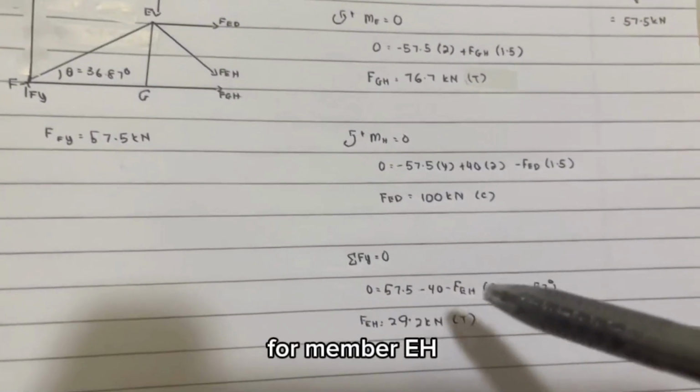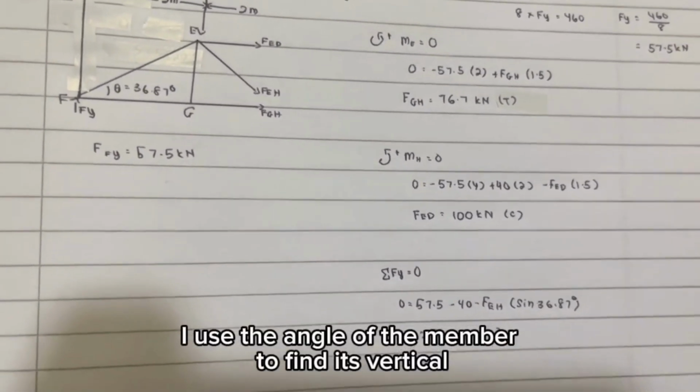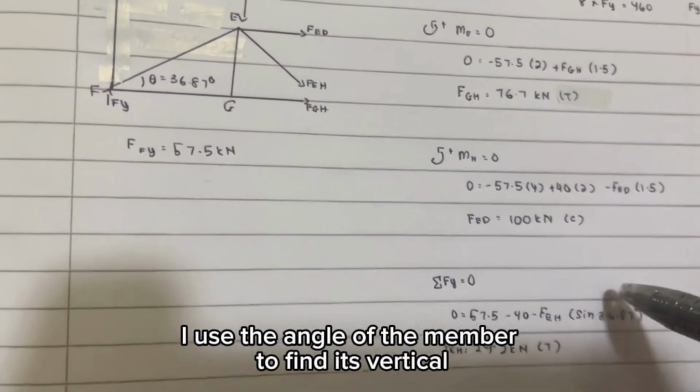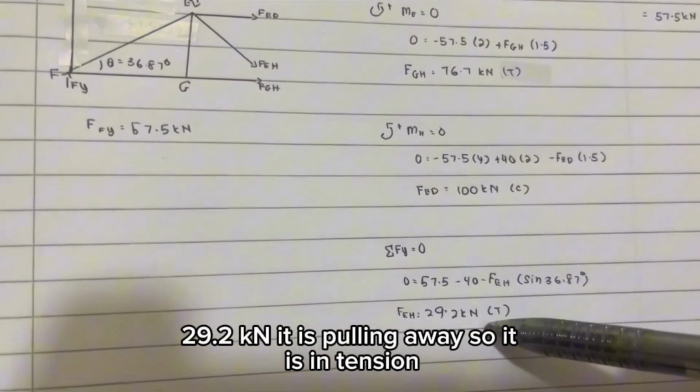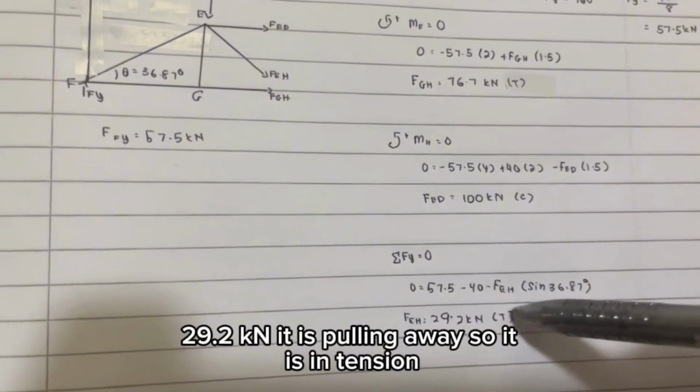For member EH, I balance the vertical forces. I use the angle of the member to find its vertical component. The result is 29.2 kilonewton. It is pulling away, so it's tension.